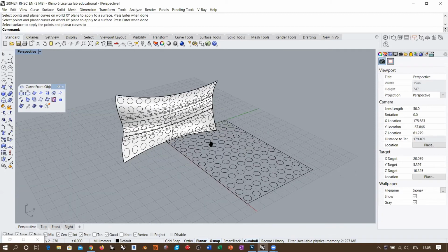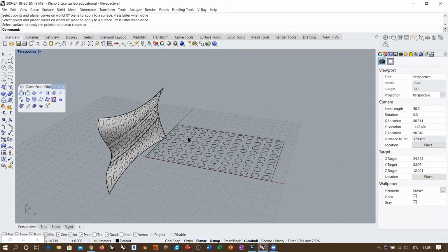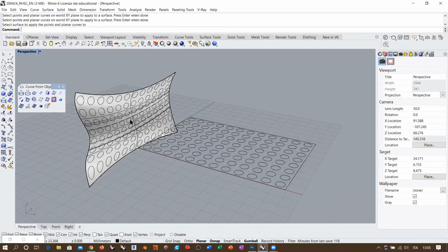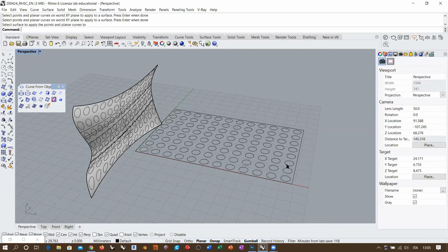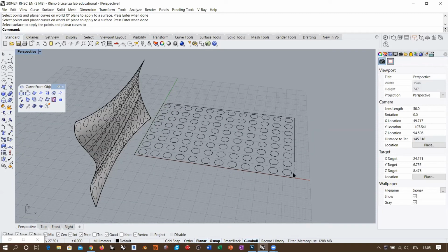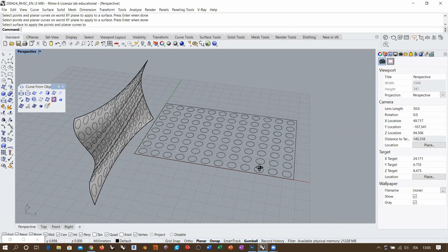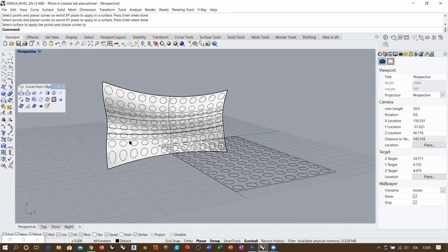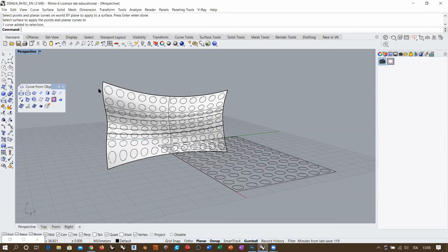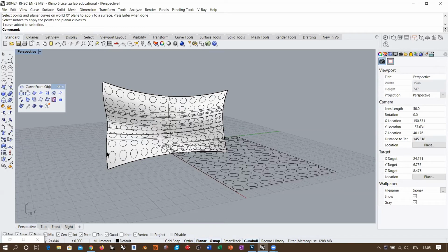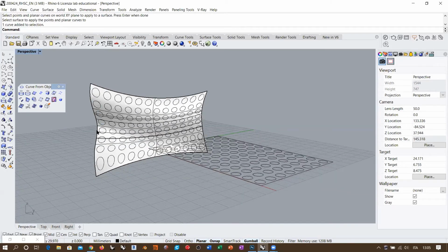So you see that UV curves always produce some deformation, because unless you have a regular topology for the original surface, there will always be deformation between a constant speed of the rectangle, which is a bilinear geometry, and a non-constant speed of this kind of weird topology that we have here, which depends on the topology of the cross-section. Okay, remember that this depends on the topology of the first cross-section, which had those knots added in the center part.